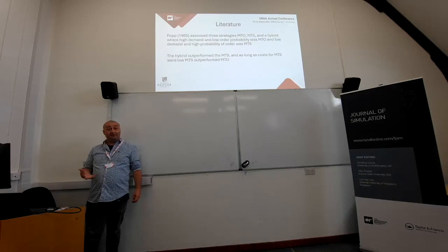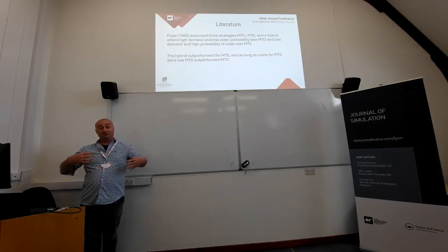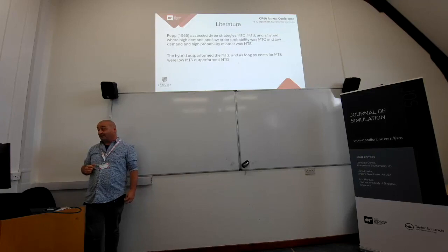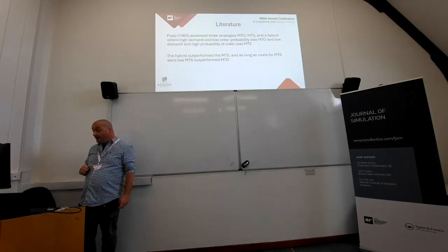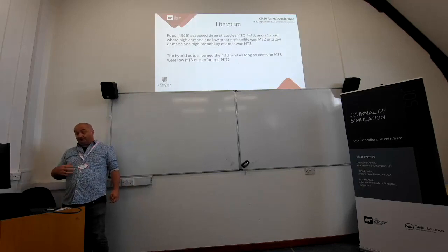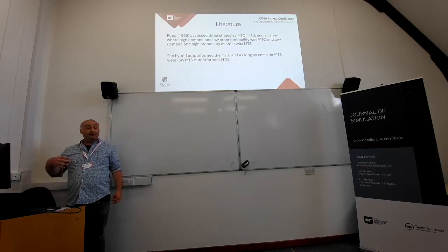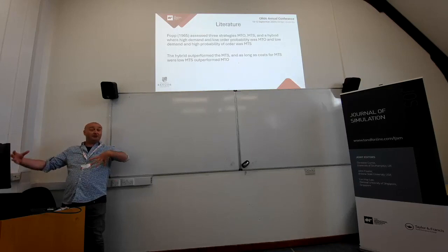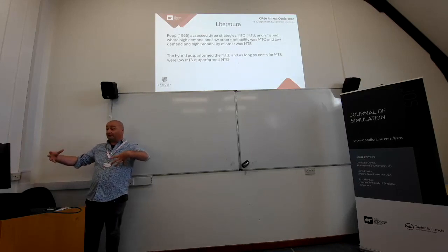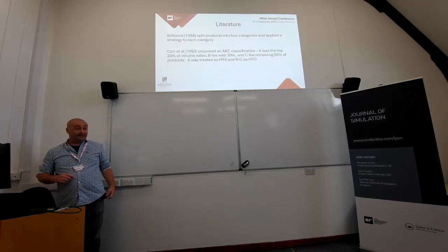So in terms of the literature behind this, some of the earliest work on hybrid approaches was in 1965 by a chap called Pop, and that fits in with computing technology becoming more available academically, so they were able to run simulations much more effectively than before. What Pop found was that the hybrid approach tended to outperform make-to-stock on its own, and that as long as the make-to-stock costs were lower than the make-to-order costs, it would tend to outperform running strictly on a make-to-order approach.